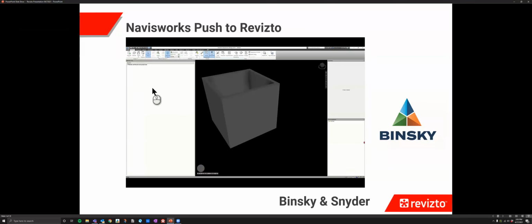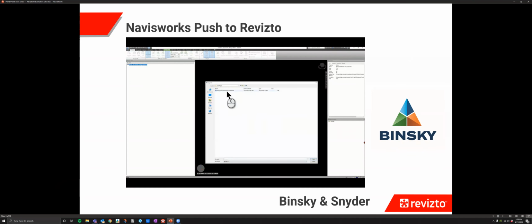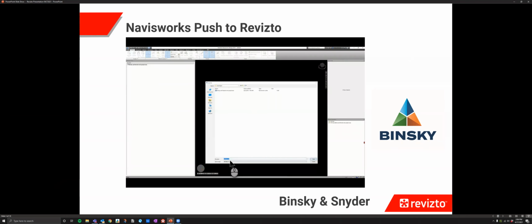Right. And that's basically what happens: our company standards, we push all contract models through Navis, and our stuff that we draw, our pipes and small equipment that we put in Revit, gets pushed through the Revit exporter to Revisto. So you have all the contract stuff from other trades, usually HVAC, architectural, structural. And here what I did was I just drew 4 little walls up in Revit, NWC'd out, pushed it into Navis. And of course, you got to save your Navis project. This was just a test, so I probably just named it test.